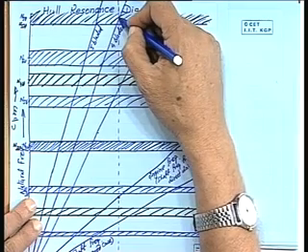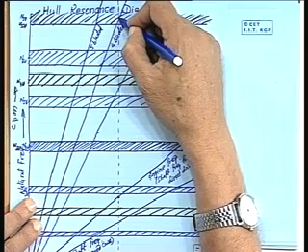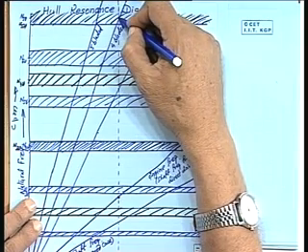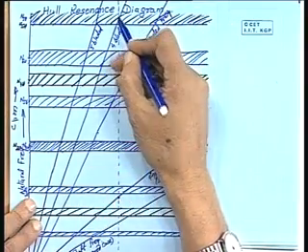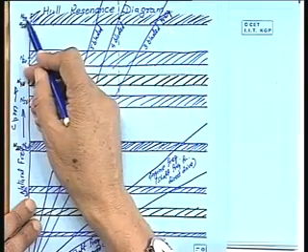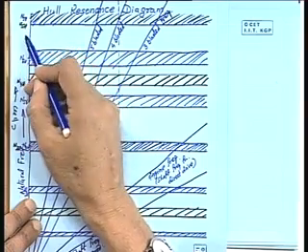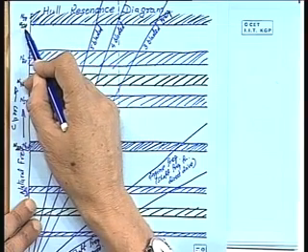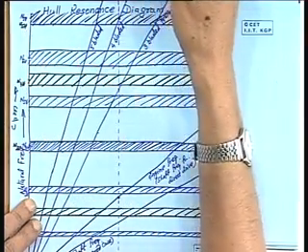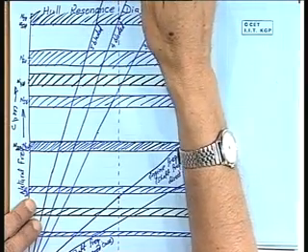Come here, the 4-bladed propeller, if you put onto this to get the output, then it is likely to excite 7-noded vertical and 5-noded horizontal vibration. Beyond that I am not considering, so 5 also it will be clear of, because I am not giving importance to that because of my guidelines.